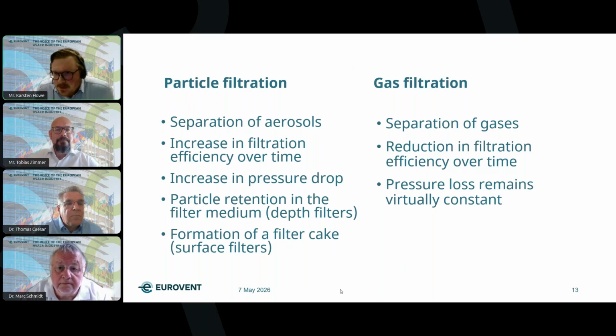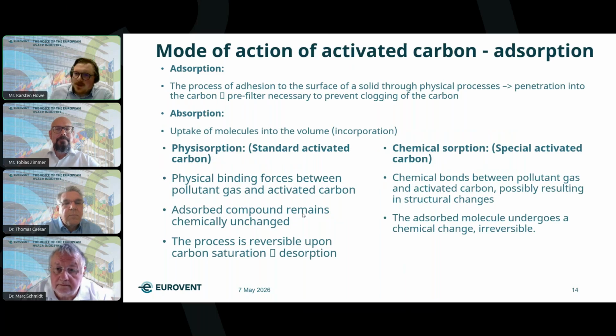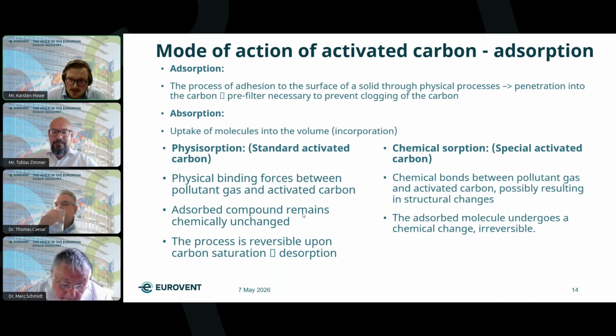Yeah, then a little bit of theory, mode of action of activated carbon. We are talking about adsorption, not absorption. Adsorption is the process of adhesion to the surface of a solid through a physical process, so it gets no penetration into the carbon. This means a pre-filter is necessary to prevent clogging the carbon with some aerosols, which we don't want to have.